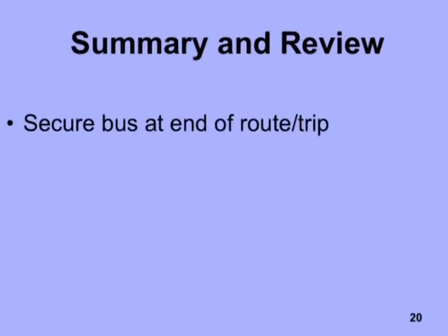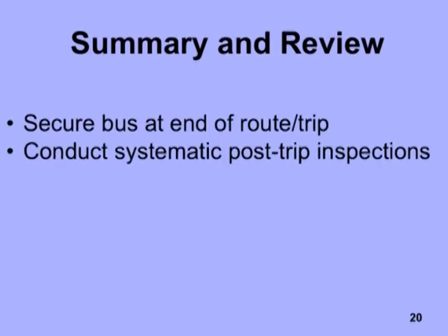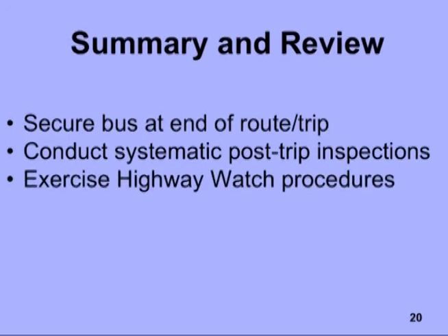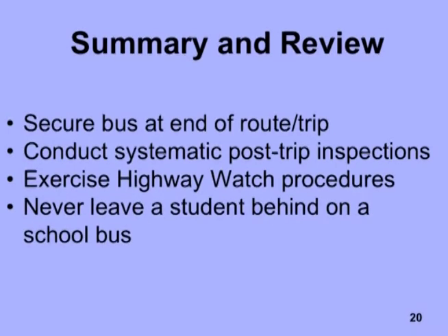In conclusion, let's review the important points for our instructional presentation. Always remember to secure the bus at the end of a route or trip. Conduct your systematic post-trip inspections. Exercise highway watch procedures. That includes walking your bus on the field trip before loading students and other passengers for the return trip. Never leave a student behind on the bus. Remembering to consistently complete these tasks will make your school bus a safe place for you and your students.